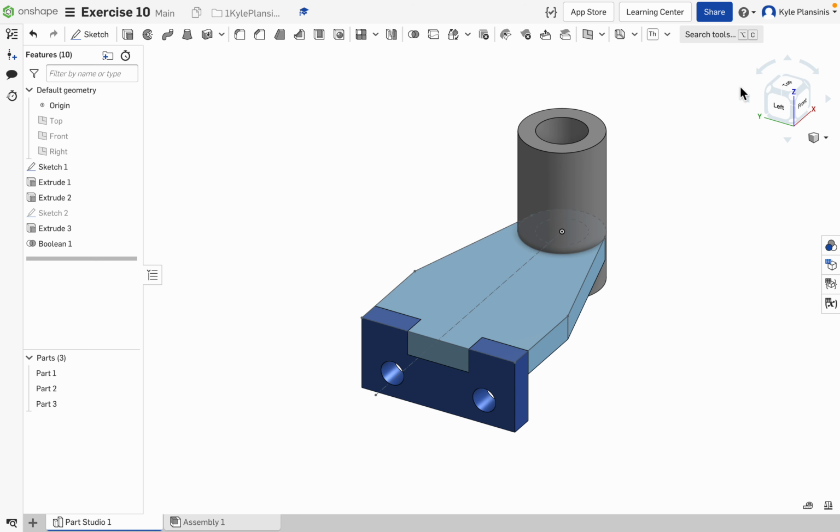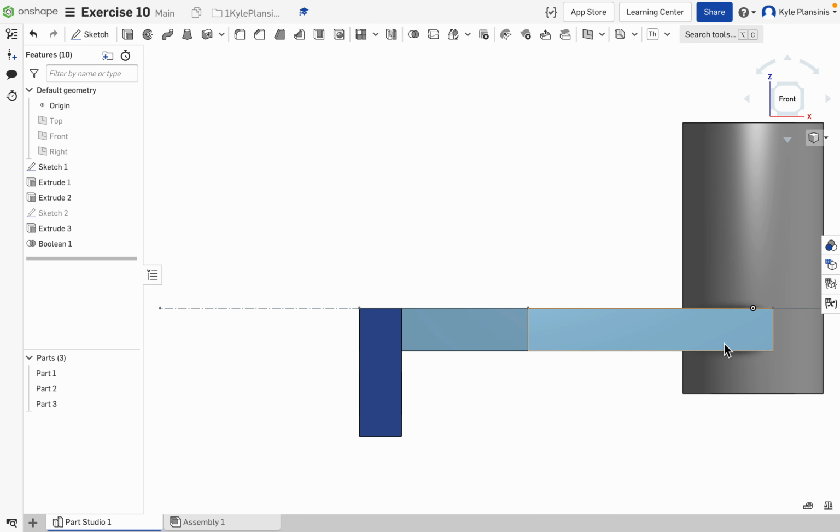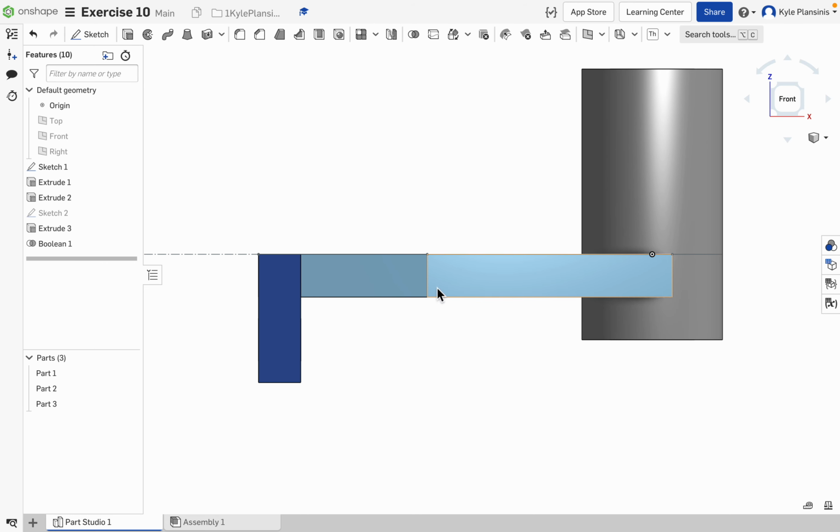So this is the whole point of all of this. When you 3D print something, if I tried to 3D print this part, where would I set it on the table? It only prints in layers, so if it sat like this, it would have to print support material under all of this because it's liquid hot molten plastic. If I tried to just squeeze it out in midair like this, it would droop down.